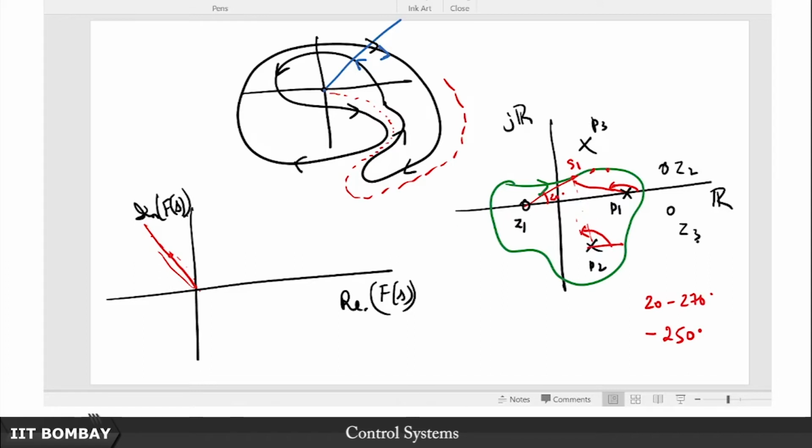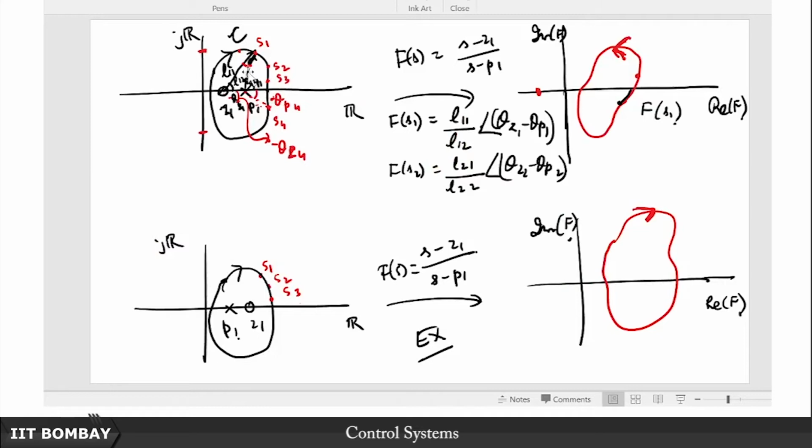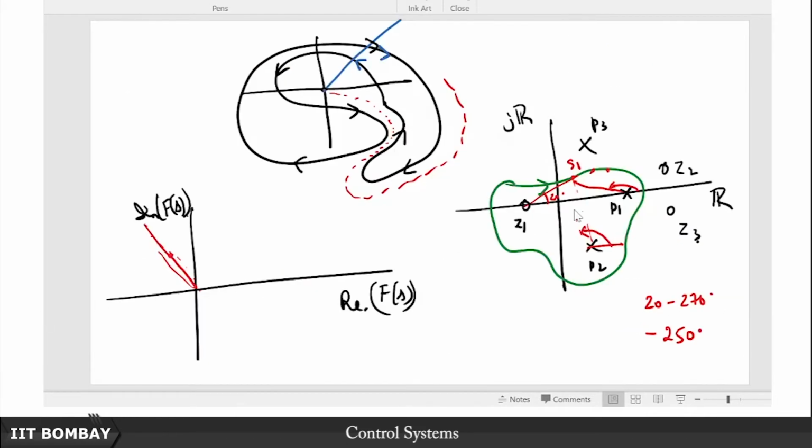So you see, unlike the one pole, one 0 case where I really know the relation between these two angles, which is basically nothing but the third angle in this triangle I have constructed, here the moment the poles and 0s increase, it will give you some polygonal sort of shape inside, and it is really very complicated to get the geometric insight. So the way to see this is, you look at the entirety of this contour, and once you have travelled across this entire contour, for any point inside this contour, the net phase change of the phasor emanating from that point and joining points on this contour is, you go once around, right.